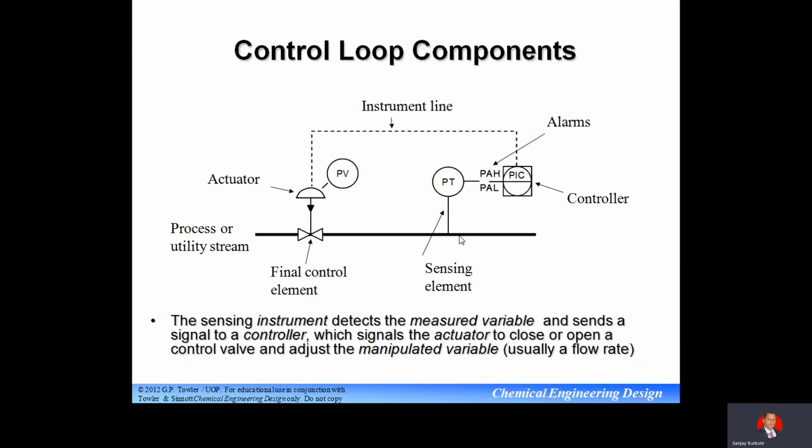For flow rate measurement, a differential pressure cell is there. So flow rate measurement can be done by using a venturi meter, orifice meter, like this. Level measurement can be done by displacement or differential pressure. These are the measurements, and we will go for reading of this.